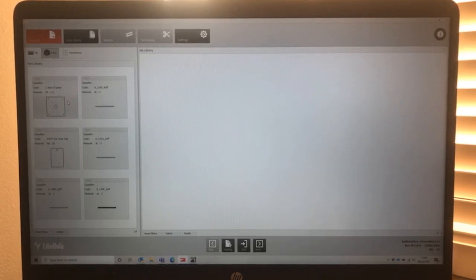So you can filter them by thickness, select a couple of the parts that you want to cut extra, and load them onto the material as well. It just gives you that added extra. It also means that if you put the part code details in correctly, as you go through different jobs and different nestings, you can refer back and pull parts in again. So if you've got specific sites, for example, where you use certain plates, you can just load them in from the parts list without having to keep loading them in multiple times. So that's where the parts list comes in useful.